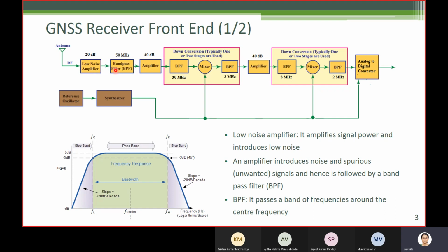This does not have any gain. It has a gain. So if this gain is large, the noise that would be introduced by this block would be small. And the same goes for this one. For this one, you have 40 dB, you have 20 dB, 60 dB gain. So noise introduced by this block would be even smaller.